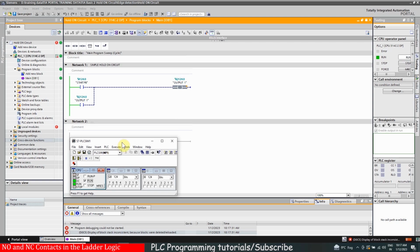Now, as I turn on this I124.0, it has turned on our Q124.0 output coil, and its contact is also closed because we have assigned the same address to this normal open contact. And from here, this output Q124.0 is latched on. If we release our push button I124.0, this output still remains on. And the next thing is that we cannot turn off our output Q124.0. Now to turn off our output, we have to use an NC contact here.